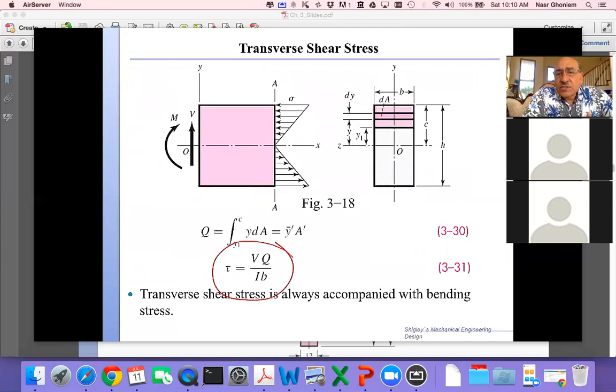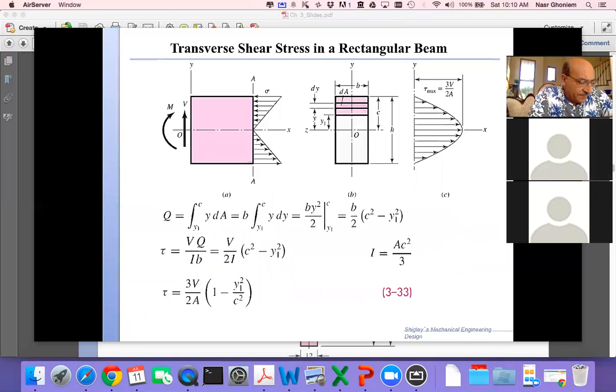First, we always look for the maximum shear. So the maximum shear is going to be when the V is maximum. So we have to be cognizant of how to compute the vertical shear at every point on the beam, the shear force diagram, and then the maximum Q, and that is really the key in these calculations. What is Q and how to find it? And the minimum B. So the minimum B is the width at any location. So let's see how this applies.